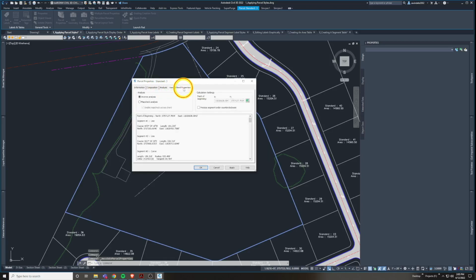We can go deeper into it here, which I do with survey analysis things all the time when I make reports or change where the parcel originates. In surveying, called its point of beginning, and it generally goes clockwise, but you can tell it to go the other way around, counterclockwise. These are important things for survey analysis that aren't exactly a big deal to us in this chapter, but I do use them on the regular when I am making parcels with different municipalities and states and counties. I use this data to transcribe information that they need to check.